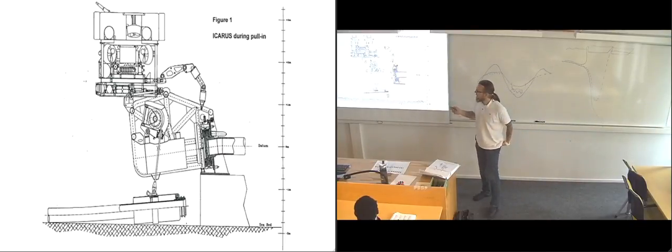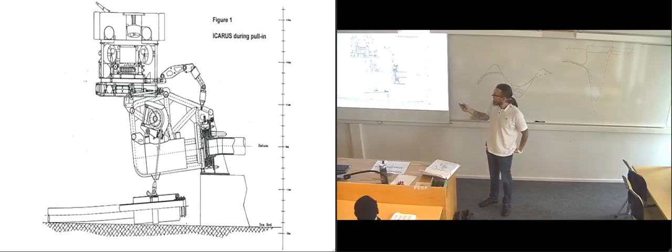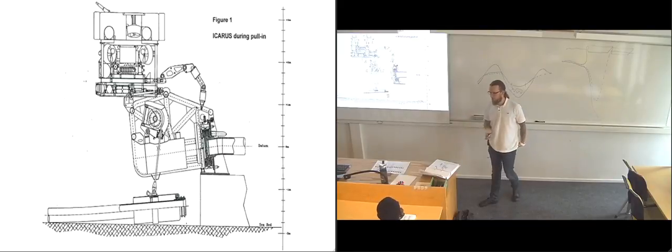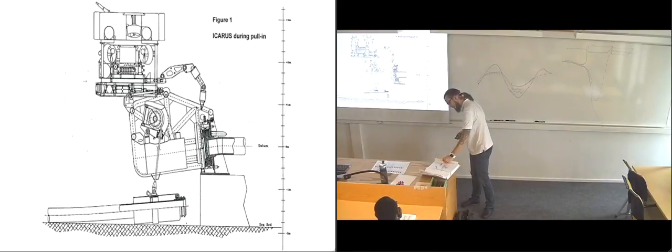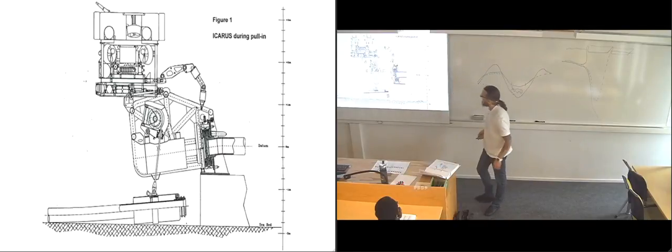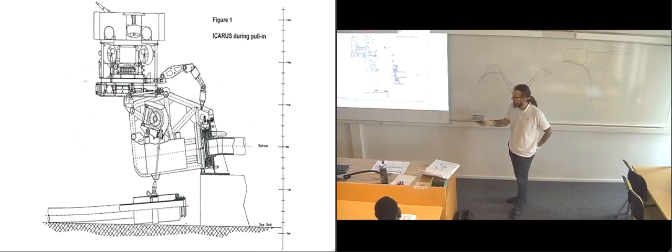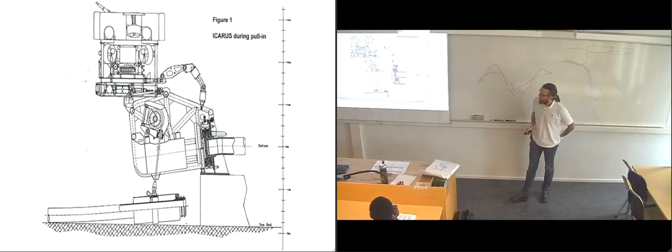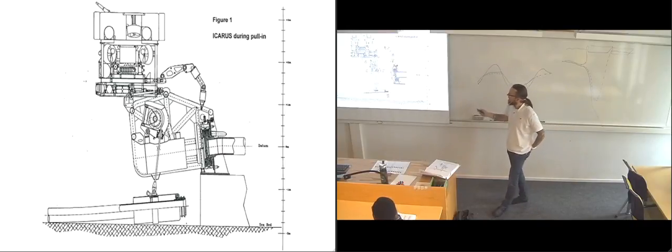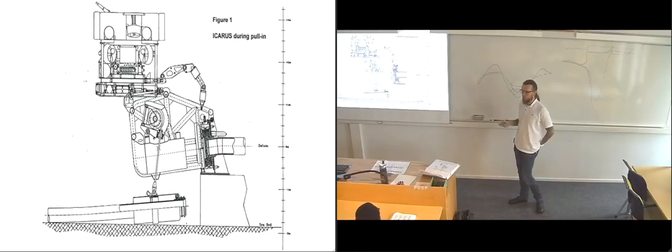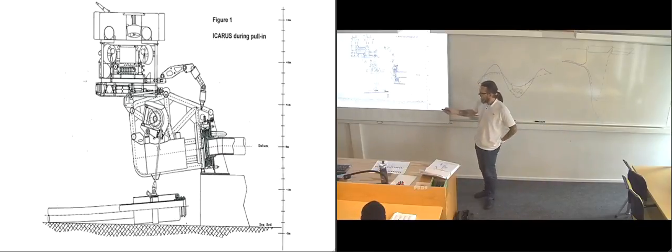So this is an ROV operated tool. So we have the ROV up here. These figures that I put up here are in the last section of the appendix, the last couple of pages there. So we have the ROV up top here, and this part here is the Icarus tool itself. And here we have a flow line that's been put down. So this part over here will be the template where the Christmas trees are placed and everything. And they're going to connect this flow line to the Christmas tree.